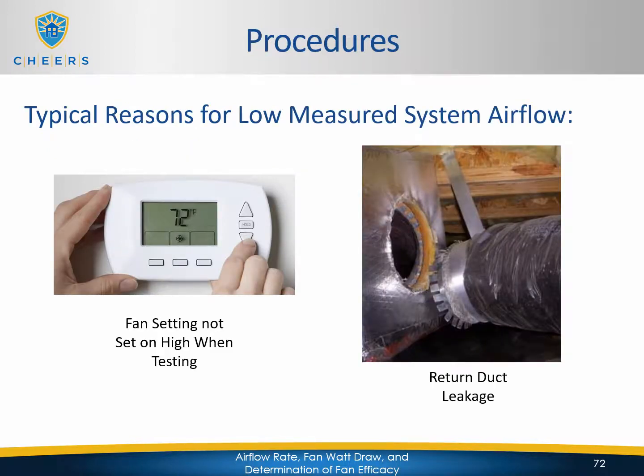So there are different reasons that you might see low measured system airflow, and these are a couple of things that you can diagnose quickly in the field. So the fan setting might not be set on high when testing. Again, you have to test the system in the highest setting possible, and generally speaking, it is the cooling system.